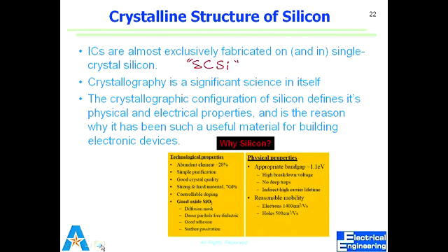And do we get control over conductivity or not? High breakdown voltage takes a certain voltage before we can bring it to conduct. No deep traps, indirectly high carrier lifetime. We'll look at carrier lifetime later on. Mobility for both is reasonable. We'll look at mobility also, and why that value is important. But essentially, silicon was used for the oxide, and everything has been good about it.